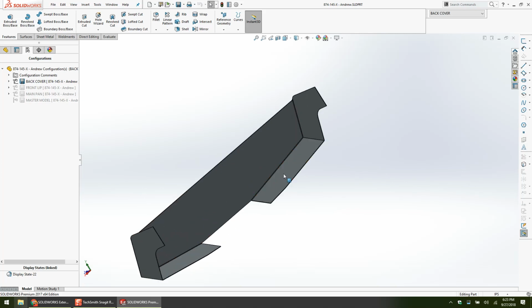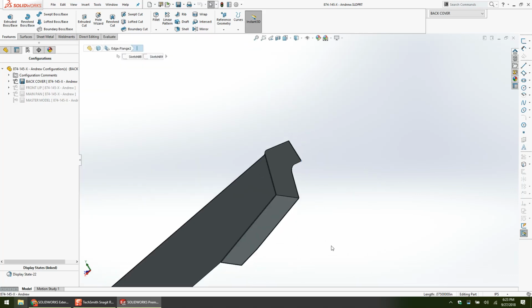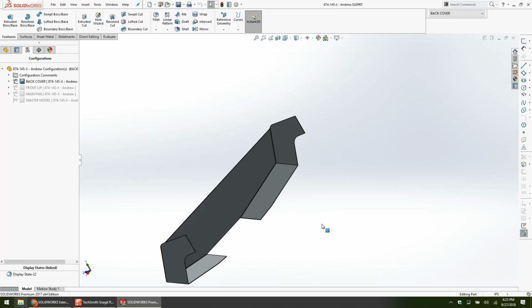And no, this was also a different exercise as well. But particularly with sheet metal design, I'm straying from external references a little bit. You want to bend the longest side possible, weld the shortest side possible. If you can figure that out in sheet metal, like who's ever welded, I don't know, 16 gauge sheet metal or something, 12 gauge, 14 gauge. Who's ever welded like 3 feet of 14 gauge sheet metal?